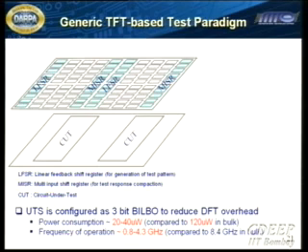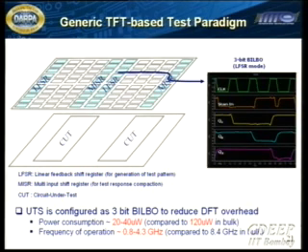And it turns out, and this is actually some of the simulation results that we built, we modeled the devices with the new scaling methodology, and then we were able to characterize and simulate these devices to show that yes, it's possible to have reasonable power consumption, in this particular case for testing some of these multipliers that we looked at, of about 20 to 40 microwatts. And the frequencies of operation varied quite a bit, from 0.8 to about 4 gigahertz.